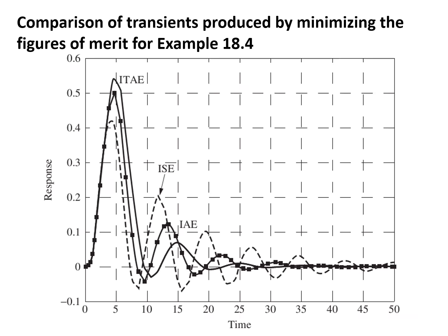And if you look at the other three methods, the ITAE, ISE, IAE methods, you can see them. The ISE method gives lower overshoot, the ITAE method gives higher overshoot, but at the end of the day, all of them damp down, going to the final value with offset 0, because it's the PI controller. But how it goes to the offset 0 is different in each way.